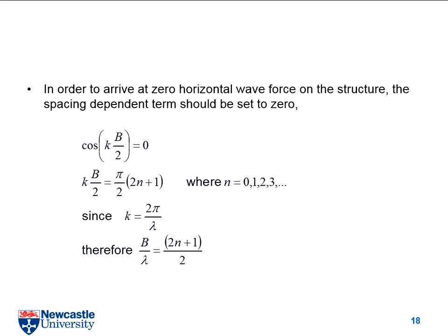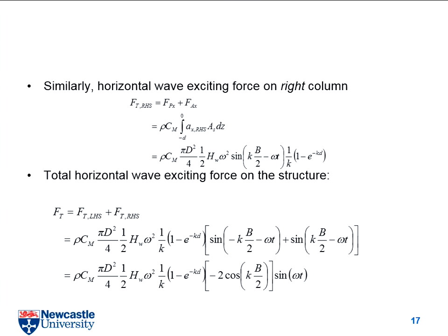And here is our wave number. It's from the previous question. You can't change the weather, but we can change our design. So if you have a good design, according to the definition for wave number, it's here. 2 pi over lambda is the wave number. But anyway, if we put them together, we will know that in this design, if the distance is 2n plus 1 multiplied by lambda, it will be 0. If we go back to the whole expression, the total force will be 0. It means it will not have any horizontal motion, right? But actually, in real case, we don't have this one. But if just in mathematical ways, we can have this, okay?